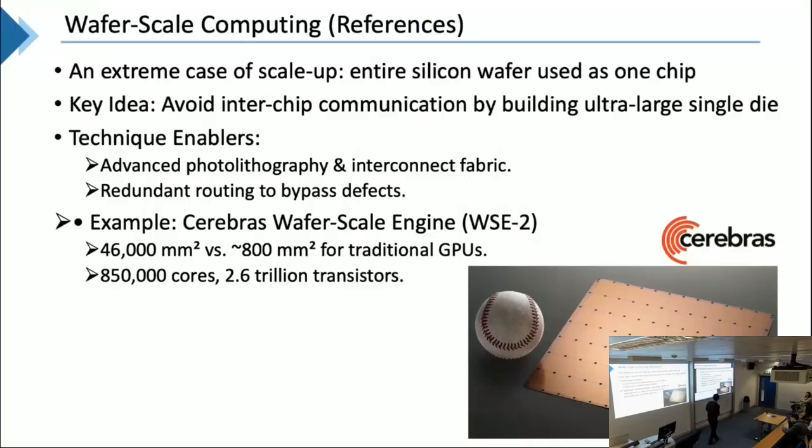100 chips. So the idea of wafer scale computing is, instead of having these small chips and taking them out, they put everything into one wafer. And even if some of the chips become defective, you can still use your advanced compiler and routing strategy to avoid using these defective chips. So this is very advanced knowledge about wafer scale computing. It's very popular as a research direction.